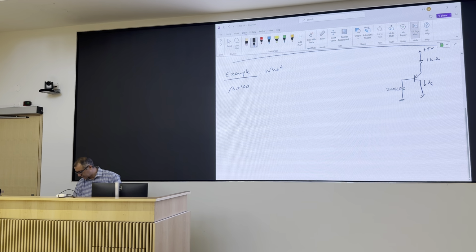So this bottom diode, the emitter diode, usually has its N side a bit more highly doped than the diode on the collector. Because of that, if you pass the same current through these two diodes, they will have different VBs. It's like they have different ISs, right? Two diodes, almost the same, so it's not exactly.